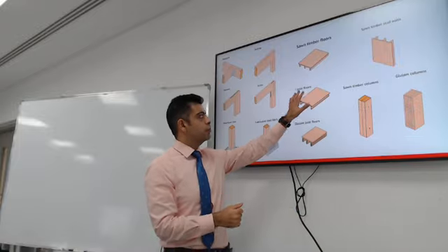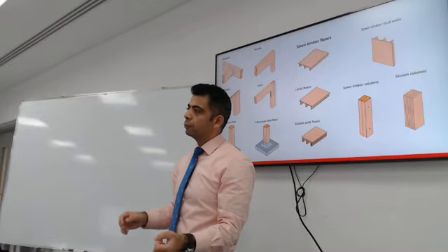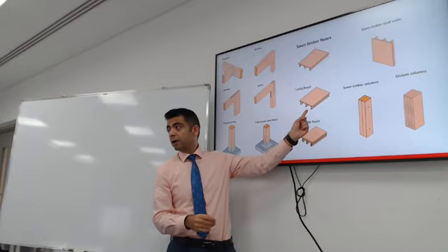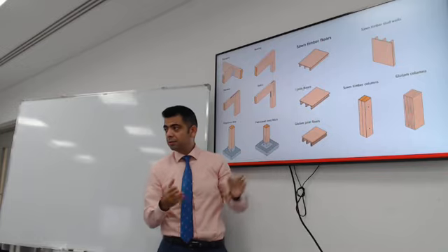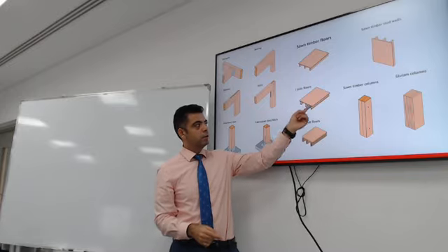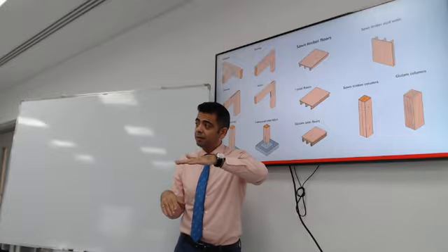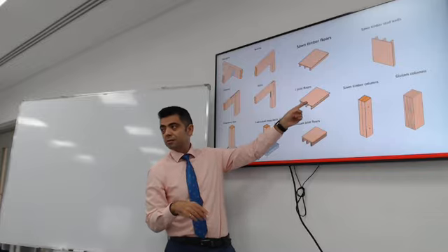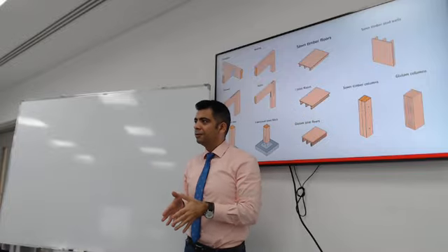These are some of the floor systems. So how do you create a floor out of wood? You can create it from I-Joists. I talked about those. They're an engineered product. You can put them at a spacing on center. And the plywood, the sheathing, the boards on top, they don't have to span that far, right? So if someone is standing in between two joists, where is the weight of that person going to go? To the joists.